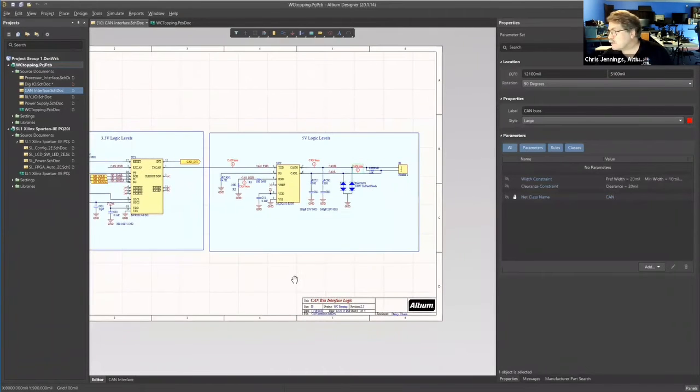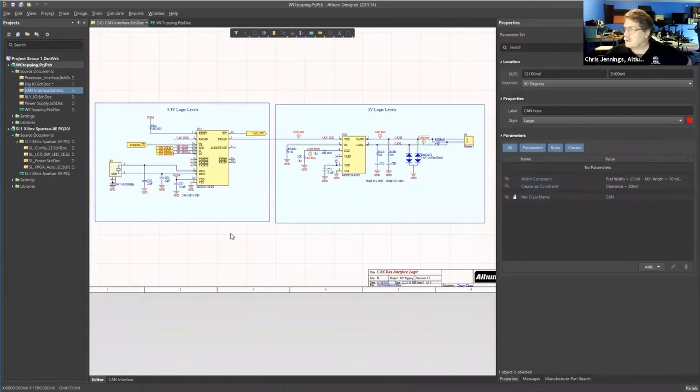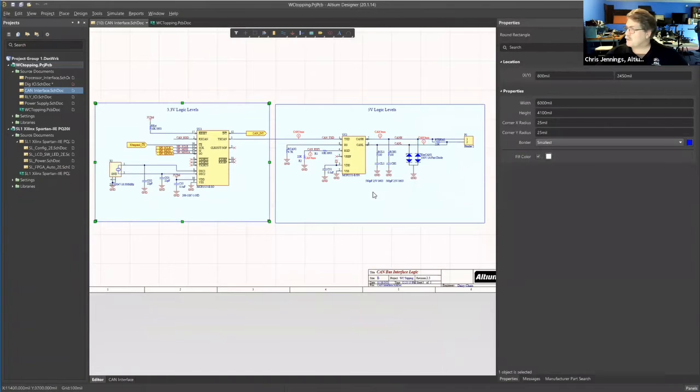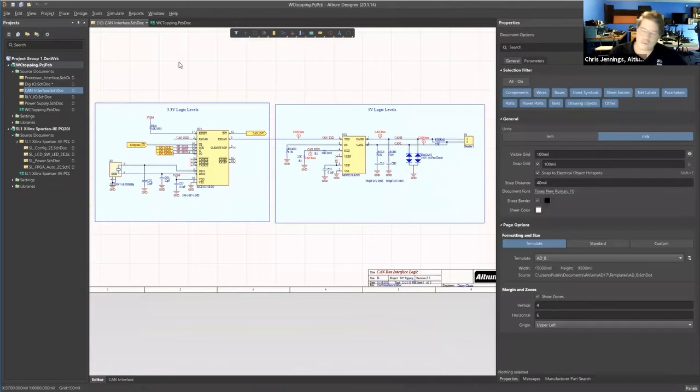And here's the other hint, aid. This block over here is all at 3.3 volts. This block here is in the 5 volt range. There is a conversion, and I needed to ensure that it was very clear what was 3 or 3.3 volts and what was 5. There's a couple places in this particular design where I was crossing back and forth.